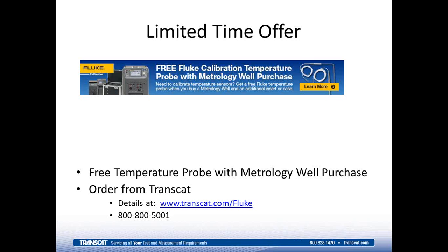So you might have to draw the thermocouple up off the bottom of the dry well, maybe a half an inch if your reference probe has an inch-long sensor in it. It's good to try to align the center of those junctions. But thermocouples are a completely different animal. The voltage is typically generated in the gradient zone of a thermocouple, so that can be a little bit of a challenge. But it's a good rule of thumb, as we illustrated with RTDs, to insert them fully and then maybe draw them off the bottom a small amount.